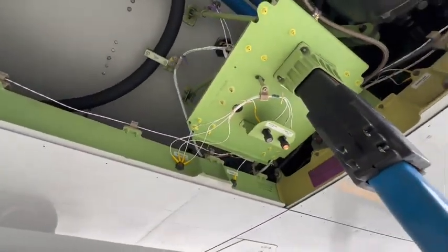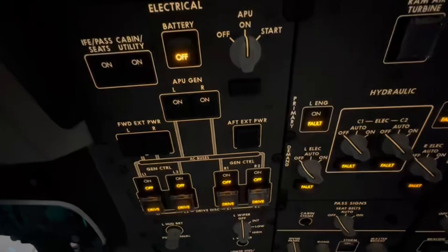Now, that being said, let's go back to the electrical panel because there's important things within the generator switches itself. You're going to see 8 switches right there. 4 of them are unguarded and 4 of them are guarded. Now, here's the difference. The top row, the 4 of them, 2 per side, are electrical disconnects for the generators. The bottom row is the guarded switches. Those are the physical disconnect. If I wanted to take a generator offline electrically and then re-engage it later on, I could do it with those top 4 row switches. On the bottom row, if I were to physically lift the guard and press one of those switches, that's it. That generator is dead. You can no longer re-engage it. You can only re-engage it on the ground. In flight, that is called an irreversible action.